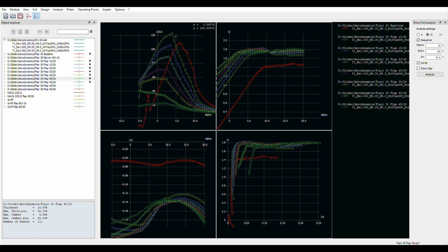You know, here was 10%, 15%, 20%, 25%, 30%, and then once you go past 30%, wow, then you really get flattened out down here and down here. So with this giant flap that they had on this thing in terms of its chord length, 45%, all they've done is ruin the performance of the aircraft and create a lot of drag.